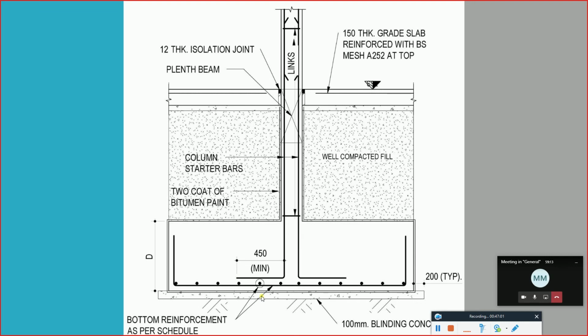So if there is any case of any shear, this reinforcement is still going to protect you, because the load coming from the top will not be distributed only to this region, it will be distributed to this particular region as well. Okay, so we talked about the bottom reinforcement for X, the bottom reinforcement for Y. We talked about the starter bars,